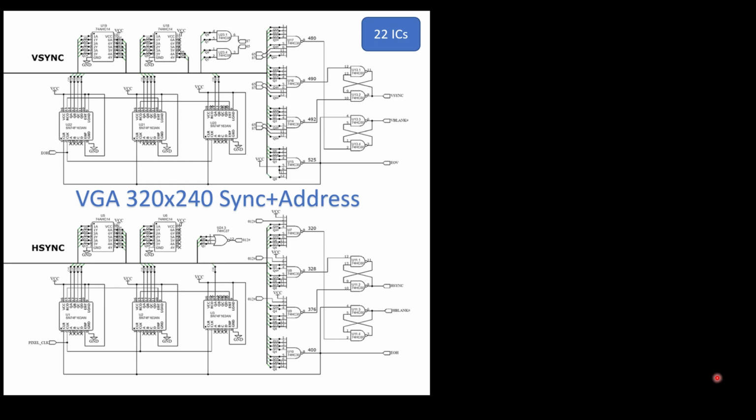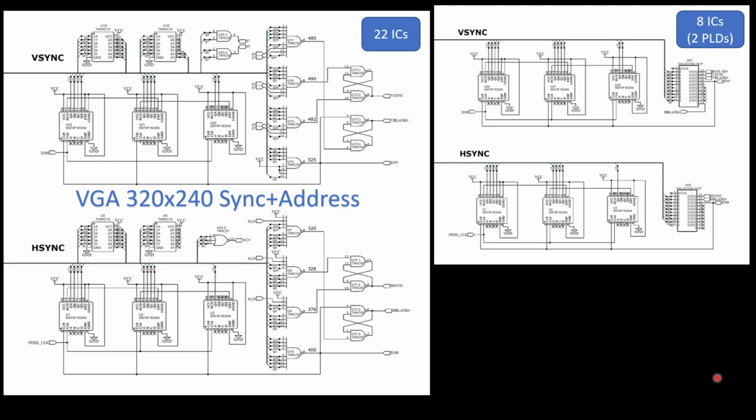Well, at some point, I decided to get rid of some of those ICs and use those PLDs, programmable logic devices, and that cut it down to this. So now I was down to 8 ICs to get the same functionality. And those PLDs work great.